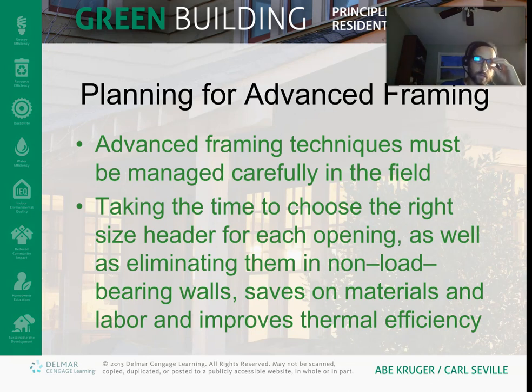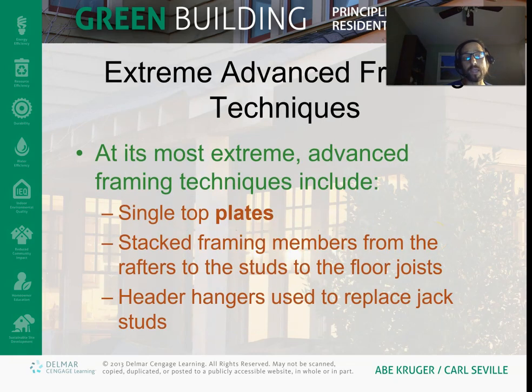It's not quite as easy to put together, I guess you could say. You have to be a little more careful. It's a little less forgiving in terms of the building itself. You have to be really careful about the loads and where you're using load-bearing walls and so forth. But it does save ultimately. It is a little more expensive to build these normally because they also usually have thicker walls and more insulation.